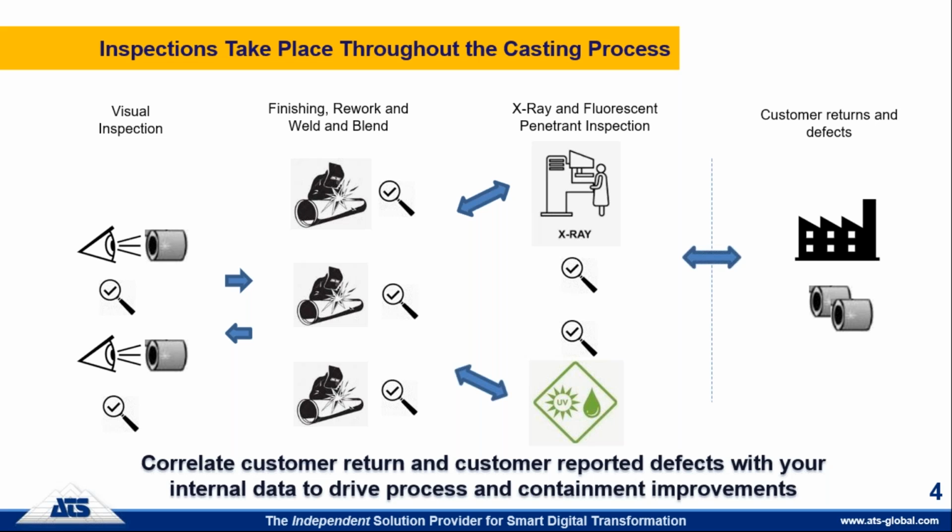If there's some failure in your quality gate system and non-conforming material gets to your customer, it is often the case that if there's a customer return, that material is logged in and inspected at that point, and what you're finding from a return from a customer is correlated with what you're finding in your process. So needless to say, there's many different inspection points. There may be other ones such as dock audits, layered audits, things along those lines.